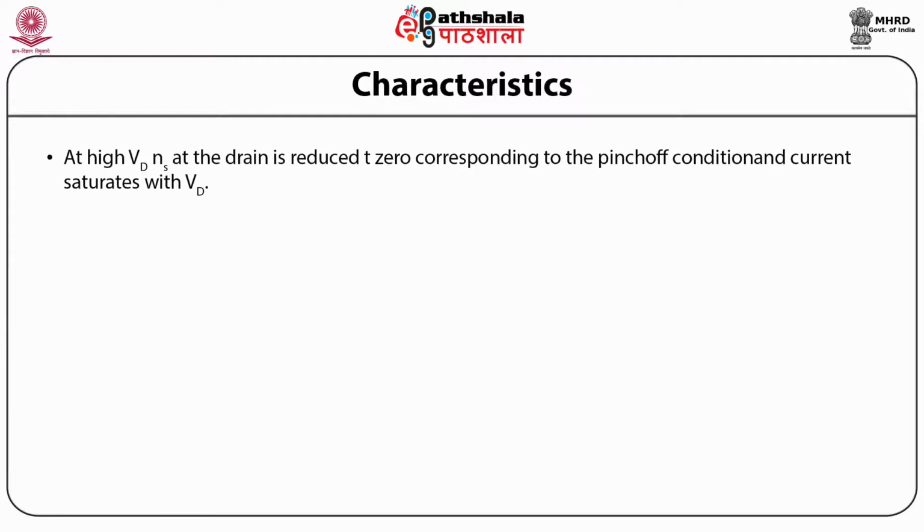So at high Vd, Ns at the drain is reduced to 0, corresponding to the pinch-off condition, and the current saturates with Vd.